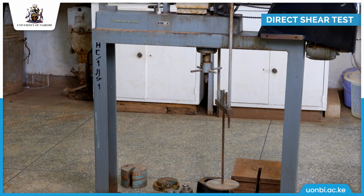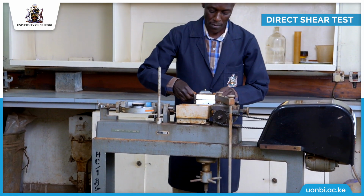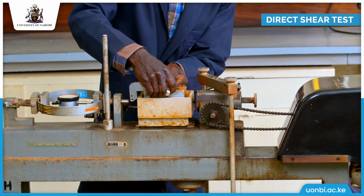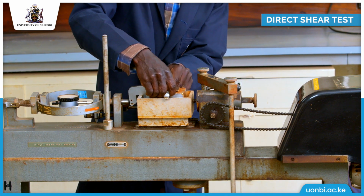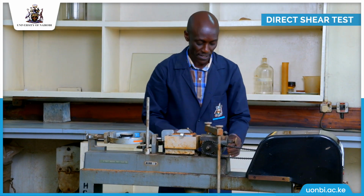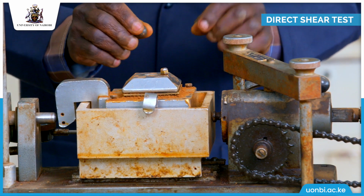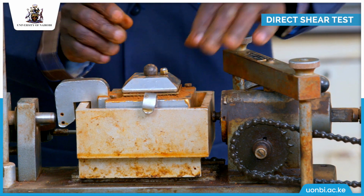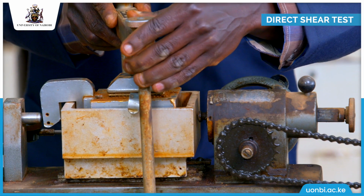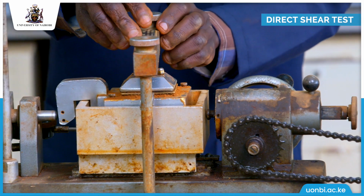Then the next step is that you take your sample and place it inside the direct shear box apparatus. When I bring the sample, I have to place it inside this rectangular box, which is inside here. After ensuring that, I have to place this steel ball on top. So I'm placing the steel ball on top, and then bring this, what we call the hanger, to rest on that steel ball, just like that.